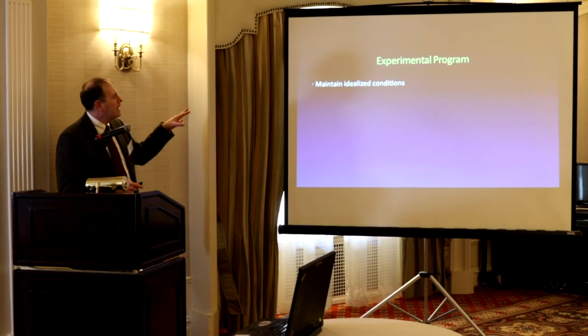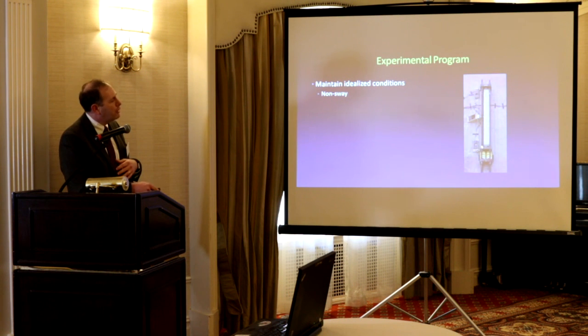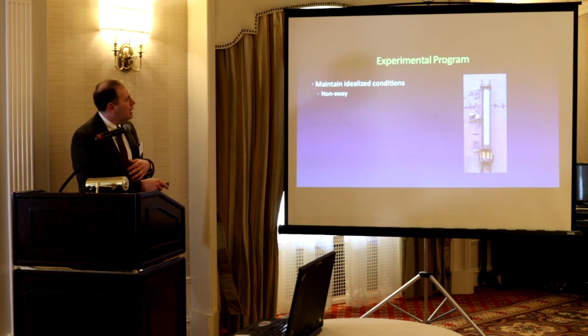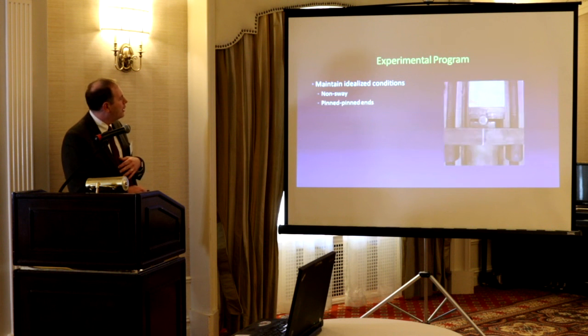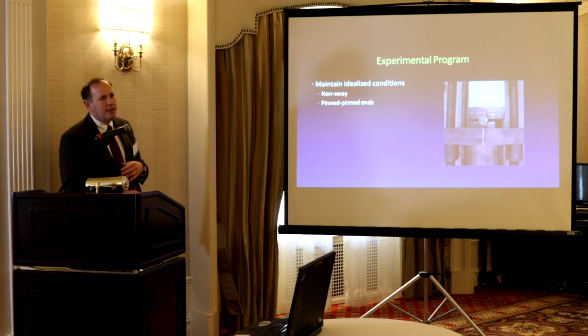So we maintain idealized conditions to make it simple to compare. We looked at non-sway. This is a picture of the frame with the loading jacks here that we load, and then we lock the nuts down here to sustain load. We measured the displacement at the mid-span. So it's a fairly simple loading. We have pin ends, so we can put in exactly the eccentricity.